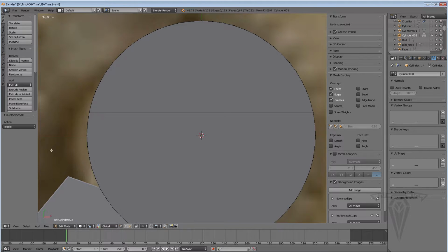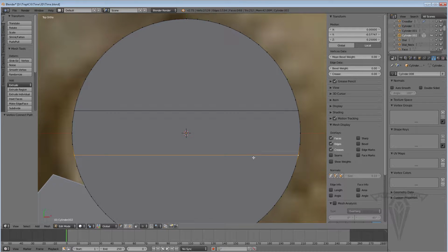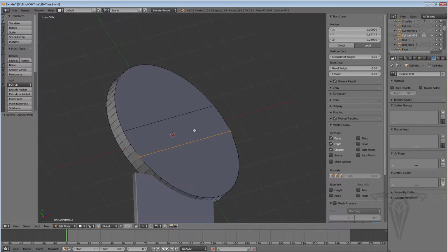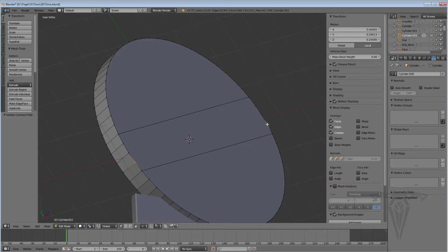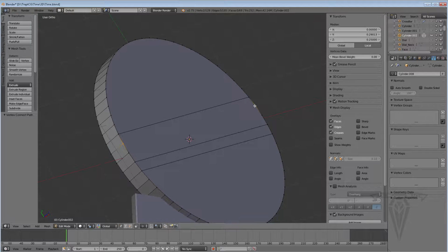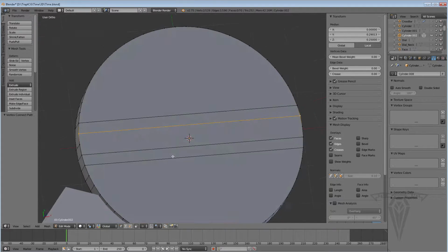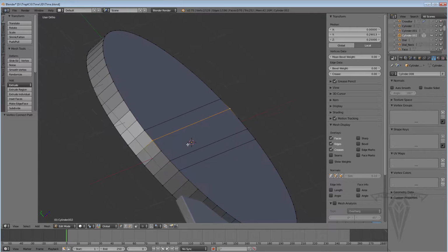Go back to my top viewport. And what we do, 2 up, so we'll go 2 down. 1, let's see, what was it from this point? Yeah, 1, 2. Okay, and J. There I have it. I have my Phillips section that I can extrude in. Now this is probably really wide. I probably should have stuck with this section here, and I can still do that. I can select these 2, hit J, select these 2, hit J, and then focus on this inner piece here. So I'm not stuck. I can even remove those lines if I have a problem with them. I'm fine with them staying.